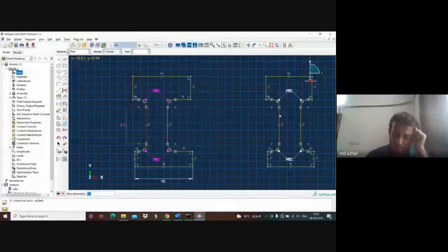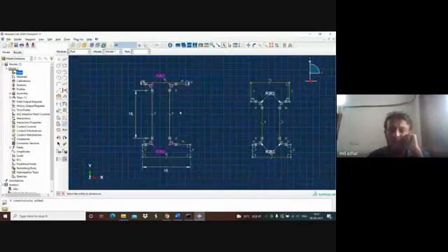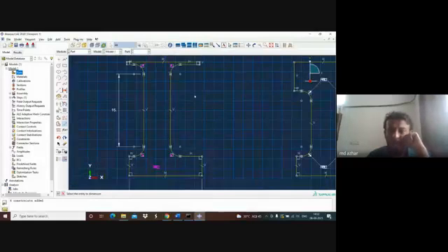Let us try to do it for 15. And you can see that this particular length is increased to 15. However, these two lengths are decreased. Okay. This is very interesting. This length is decreased, but this length is not decreased because we have selected the equal length here and we have made this one constant. However, for the top entity, we have not selected this.